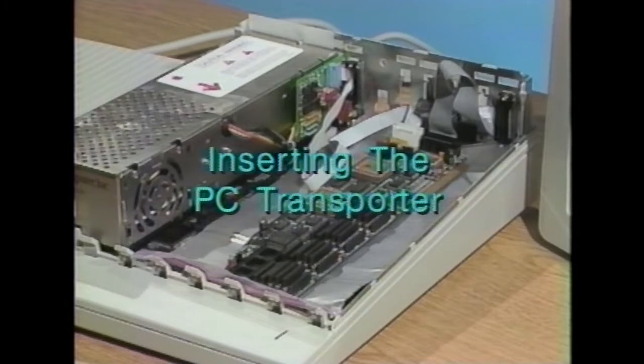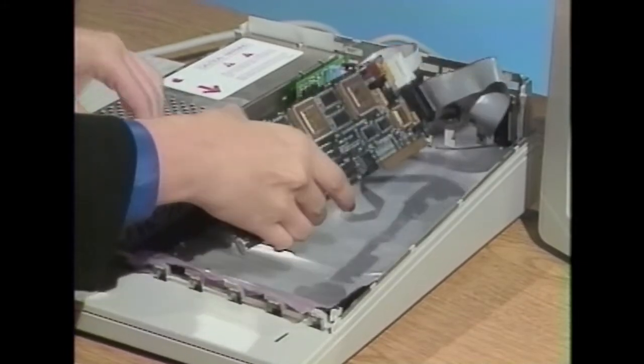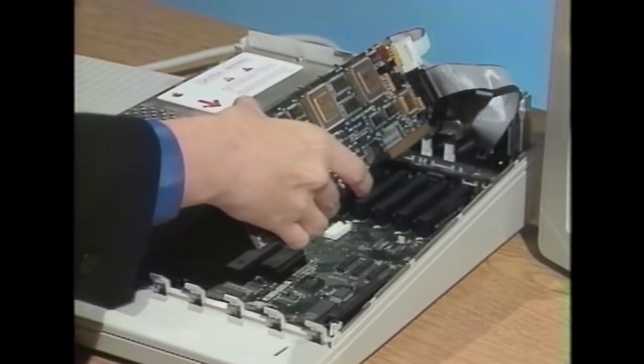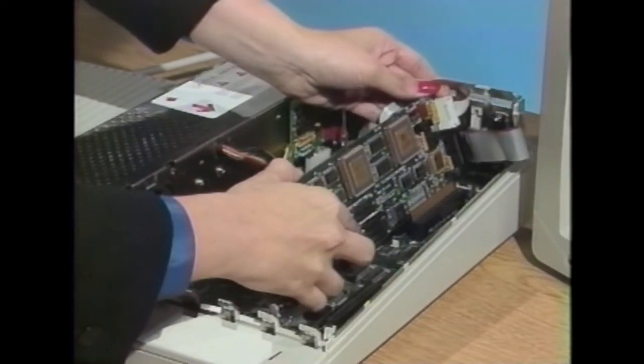Inserting the PC transporter. Now you are ready to insert the PC transporter card into its slot. Pick up the card like so. Be careful not to touch the chips or the gold fingers. Rest the card on top of the slot with the chip side toward the right of the Apple's case.